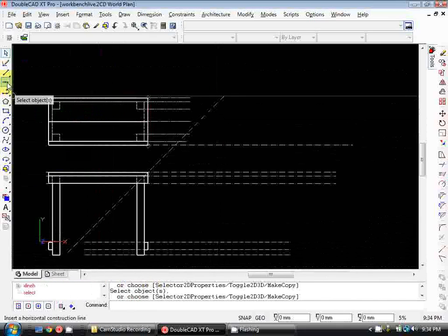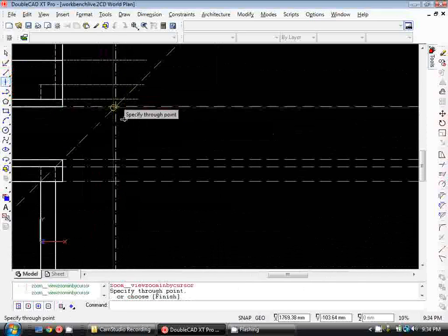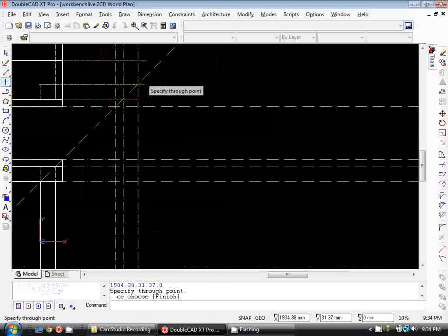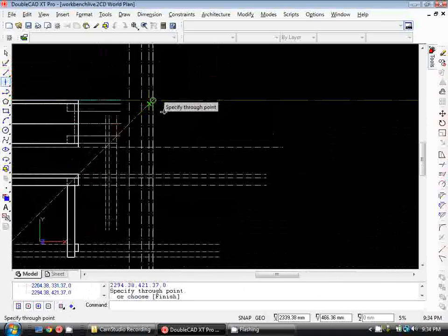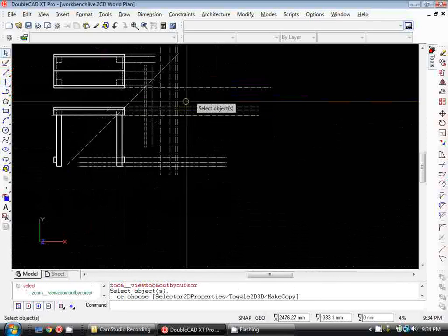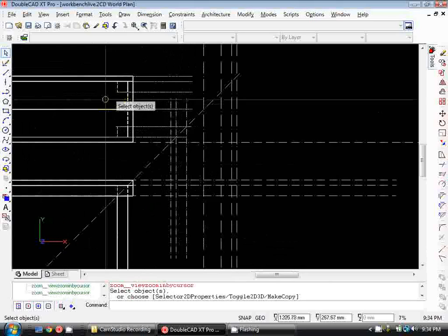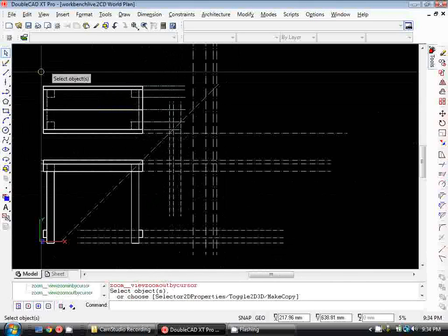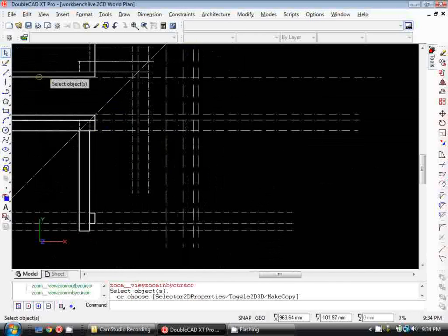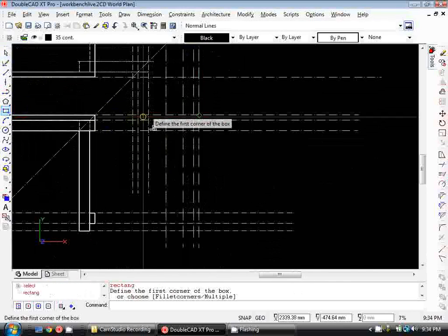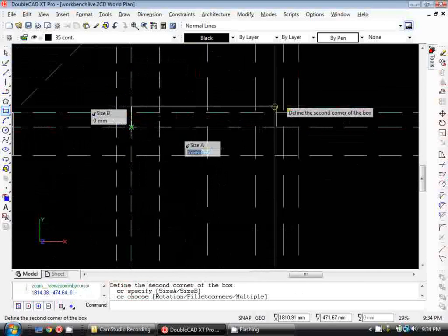and actually shoot those down with vertical construction lines, snap to the intersections on that 45-degree line. So what that's pretty much done is the same as picking up this plan view and rotating it 90 degrees so it lines up. So now I've got all of these construction lines in place. I can just quickly draw my end elevation in.